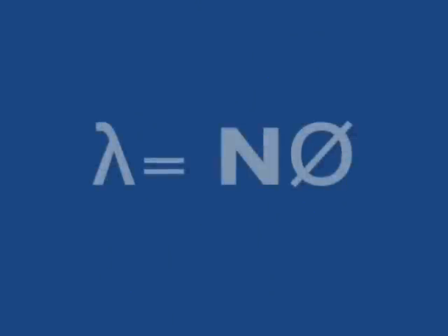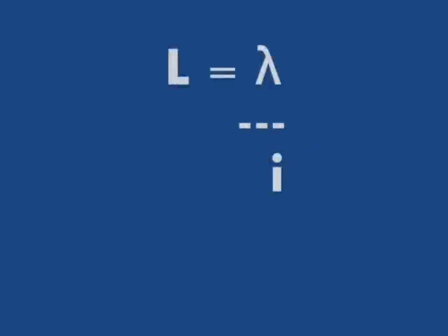A coil that is wound on a magnetic core is commonly used in electric circuits. This coil is represented by an ideal circuit and is called inductance. Here I will define flux linkage of the coil per ampere. Flux linkage, which is lambda, equals N flux. Inductance L equals lambda over I, and I and lambda are directly proportional.